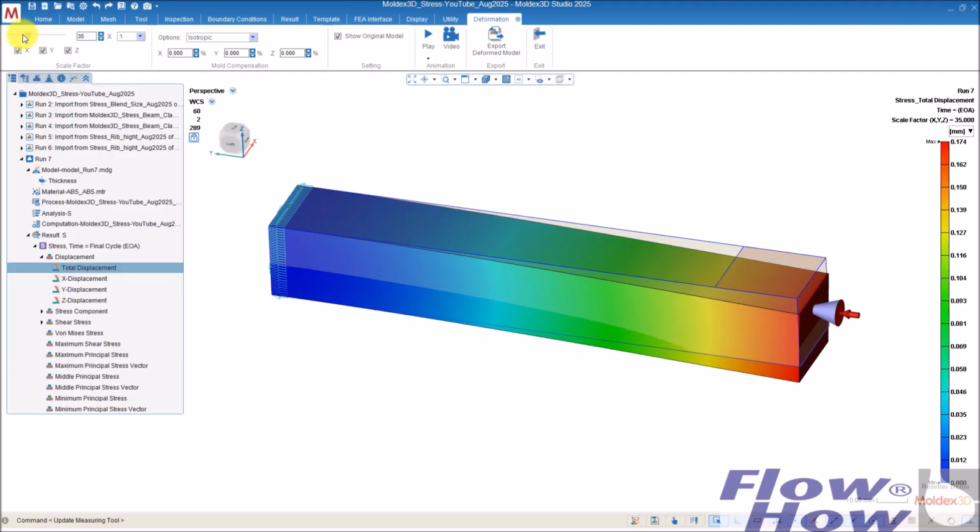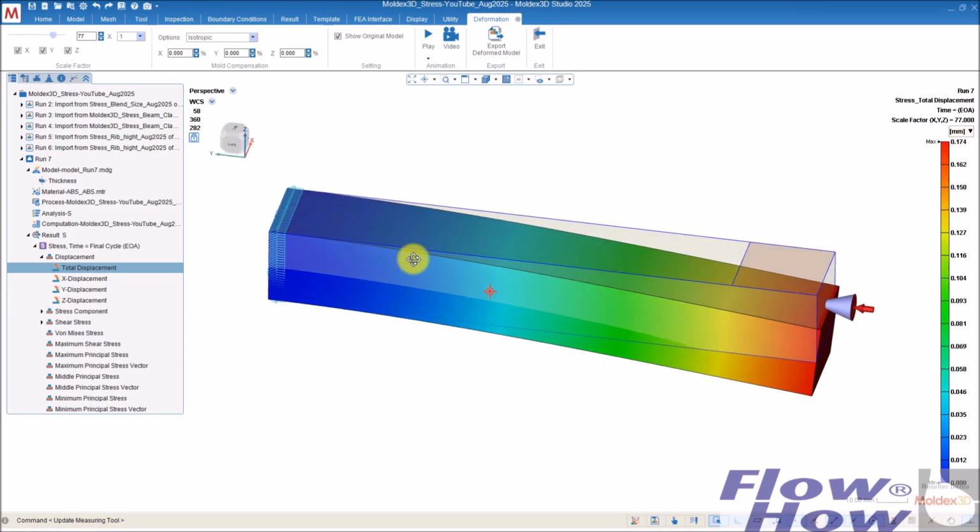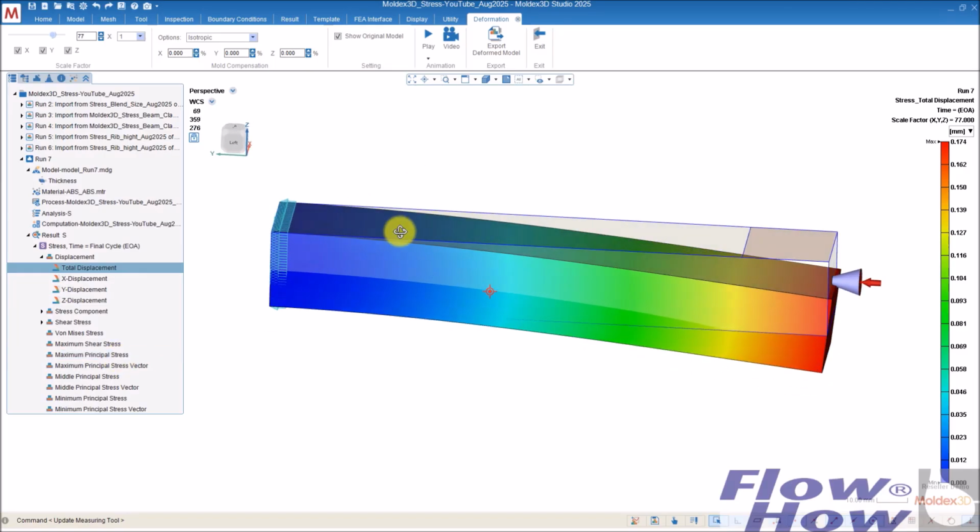It bends downwards 0.17 millimeters, and you can go, I don't know, von Mises stress is okay, good for steel normally in the linear area. You can say, okay, in some cases I will look at the maximal principal stress, but I can't dig into that too much now.